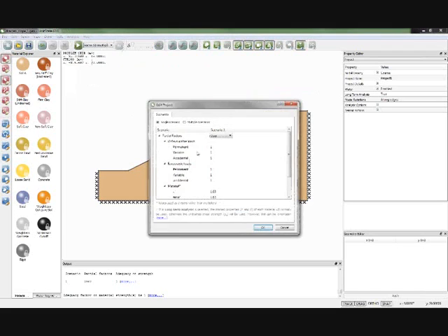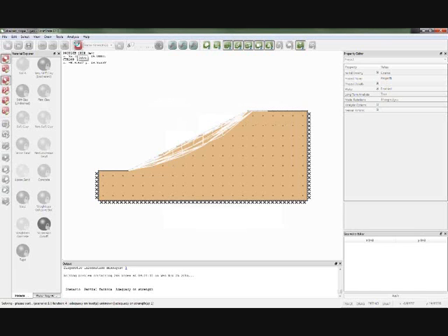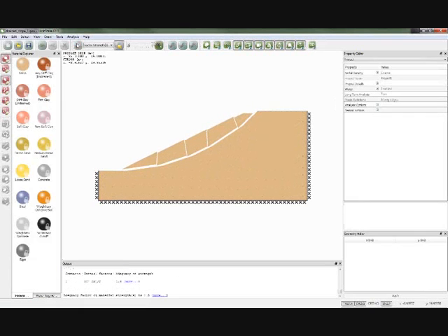Now, of course, we're more likely to want to do this for Eurocode. Now, you can type in the Eurocode values, but they are actually built in. So if I click on there, you'll see, if you're familiar with the Eurocode values, we'll pick DA1/2, which is the one that's most appropriate for slope stability. And we see the various factors there. And in particular, we're factoring c' and tan phi' by 1.25. So if I solve again, I will get a slightly different answer. I think it comes out as 1.3 when we get there. Yep. So we get an answer of 1.3.